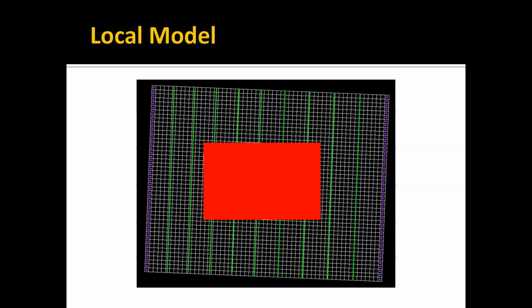There are even versions of MODFLOW where you can encapsulate one small, local scale MODFLOW model inside a large scale regional model and build a connection between the two, so that if you make changes to your regional model, the local model automatically derives updated boundary conditions from the regional model. So you can do it manually by interpolating the head values, or you can have a more structured combination. But again, if you ever have to do a local scale model and you are struggling to find boundary conditions, sometimes you have to just extend it out to the regional model.